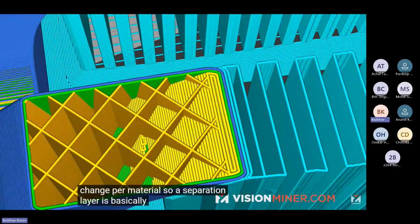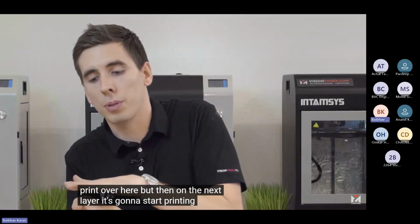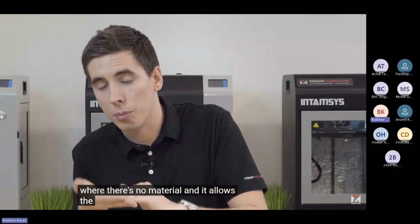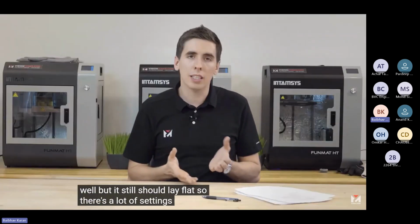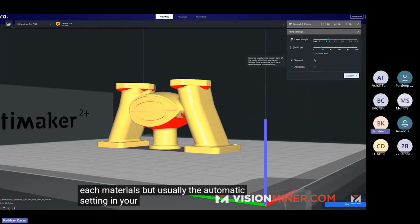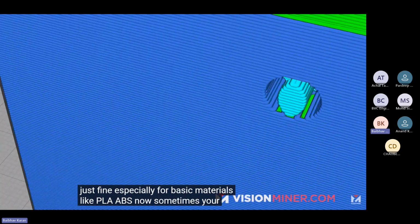So a separation layer is basically, it's going to build up the supports and then it's going to stop. And then your part is going to print another layer and it's not going to print over here. But then on the next layer, it's going to start printing on top of the support. So that's one layer where there's no material and it allows the supports to cool enough so that the next layer on top doesn't bond to it as well, but it still should lay flat. There's a lot of settings involved with getting that dialed in for each material. But usually the automatic setting in your slicer is going to work just fine, especially for basic materials like PLA, ABS.